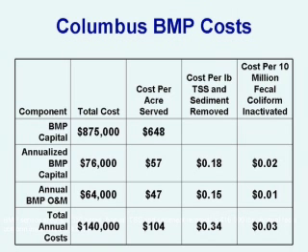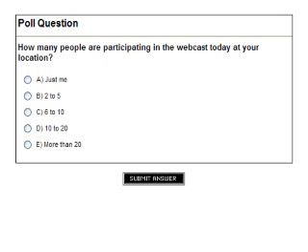And we're also measuring about 80% fecal coliform load reduction, not the 85% that the state says is the TMDL requirement, but it's enough that we feel from the modeling, and I'll show you later when we talk about disinfection, that it gets us to a geometric mean excursion below the 10% criteria. That criteria is not a part of the standards right now, but it's a part of the impaired water listing protocol.